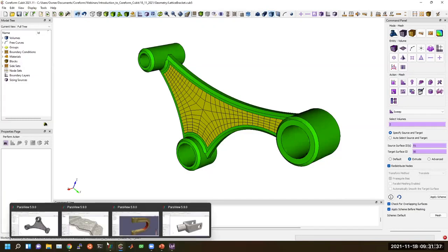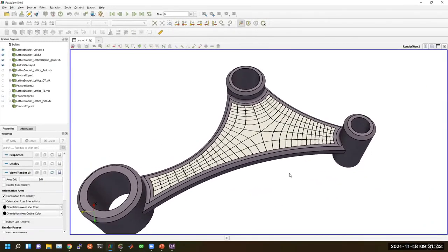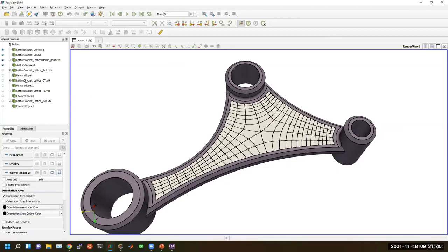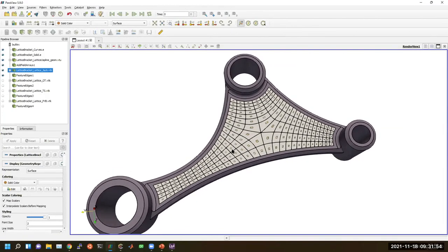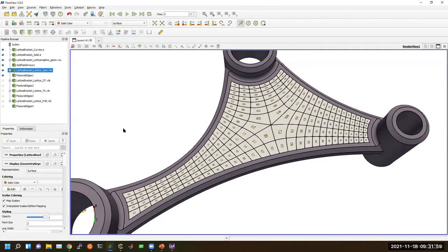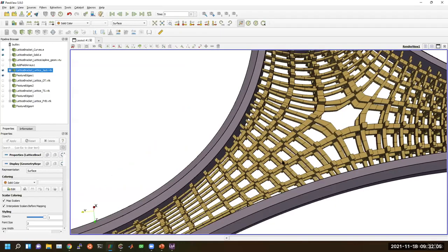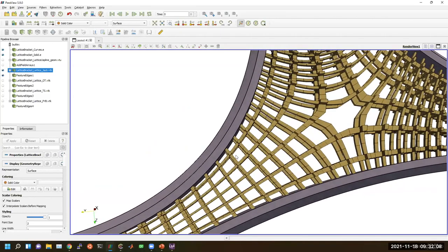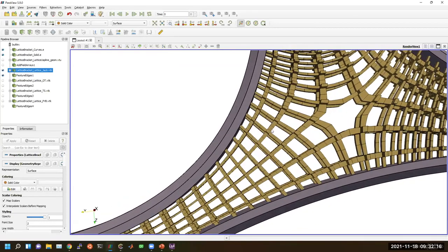And I've also pre-rendered some of these lattice structures for us here. Again, in ParaView. So we've got our background mesh. Just to show how these elements lay out, we can turn on this. This is a jack unit cell. We're also working on implicit unit cells as well. But you can see this jack layout, again, with smoothly varying unit cells. This is defined as a surface, but we also have unit cells that we're working on that are defined as curves with a defined profile size.